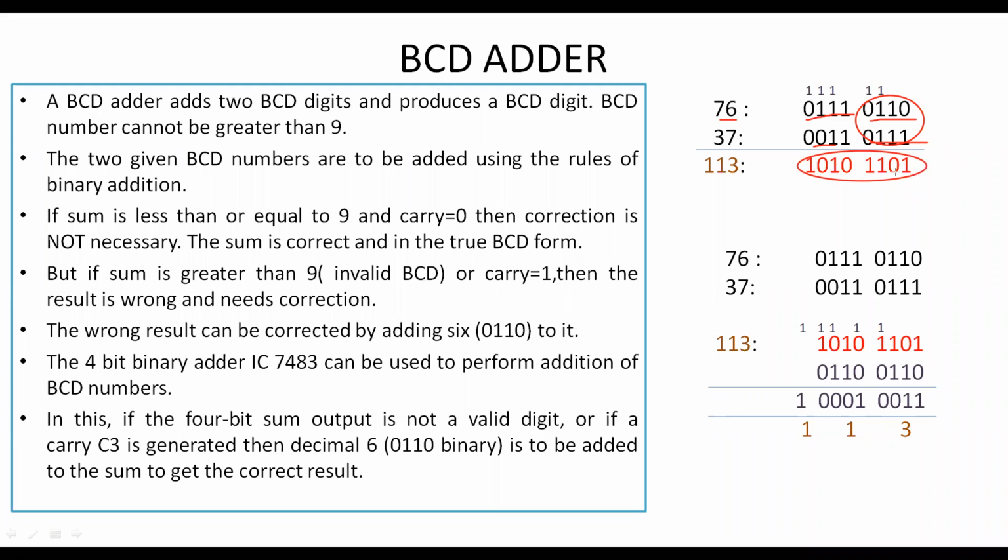If you observe each individual digit, when we check the first 4 bits, it is 1101. This is not in BCD. And I told you where BCD numbers range. In BCD, the numbers range from only 0 to 9. That is, we can write the numbers from 0000 to 1001. We should see only this range. But here, what happened? 1101, that is 13, is appearing. It is not a BCD number. Similarly, 1010 is not a BCD number. That is, when we are performing the addition of 2 BCD numbers, the resultant sum is not in BCD.